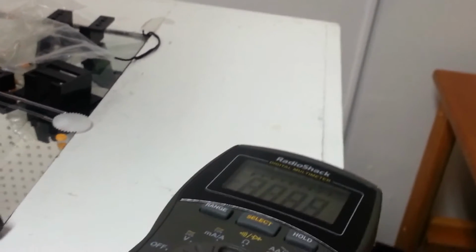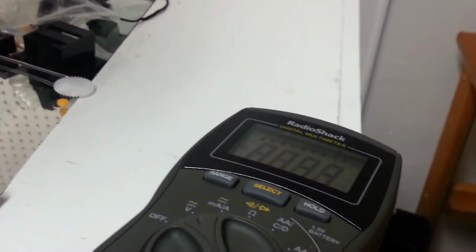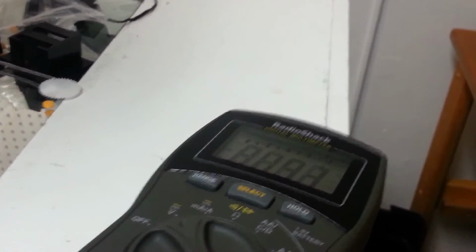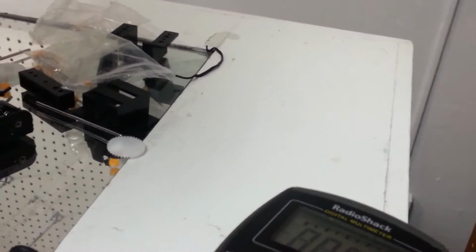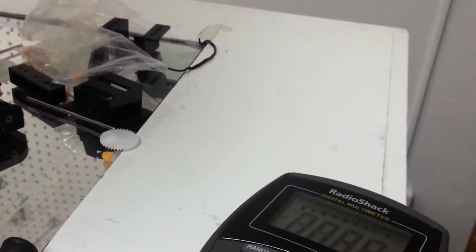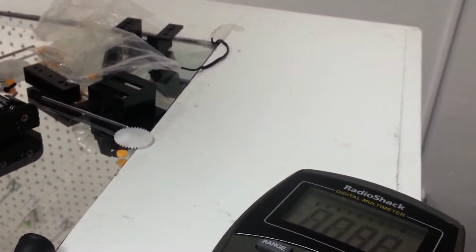And if I move over here, you can see that there's some voltage. It's not 5 volts, it's almost 1 volt, but that's power that's being generated by the second motor. So just turning that second motor is actually generating power. You can generate power just by turning any electric motor. It will generate power to the leads. Okay, so that's how a generator works.